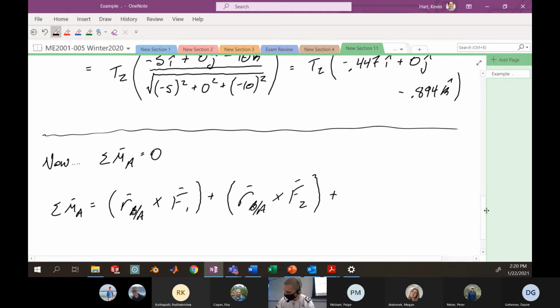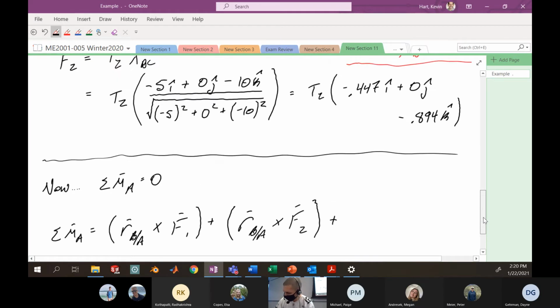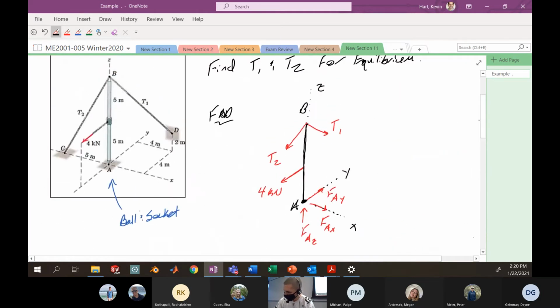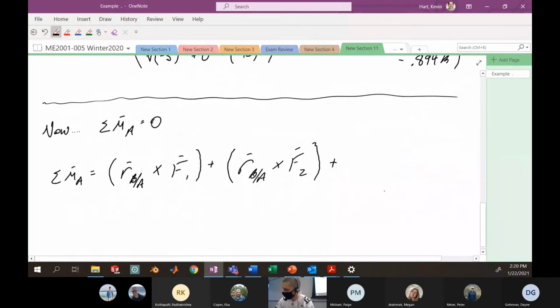And I have to add that last little bit, which is the force that's acting in the negative y direction on my post right in the middle. It doesn't really have a label for that point. Maybe we'd call that point C, just because it seems natural. If we call this point C, then the last contribution is the position vector that arrives at C from A crossed with that 4 kilonewton force. Let's just call it the force at C for now. I think that's fair.